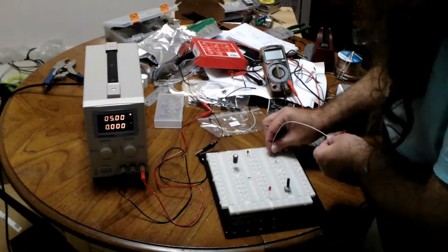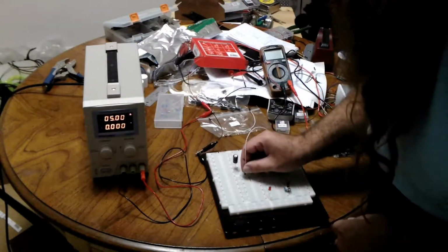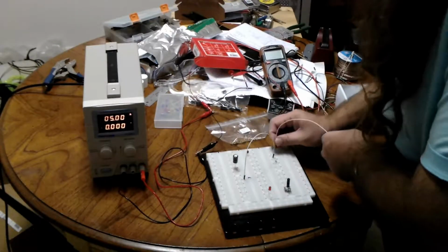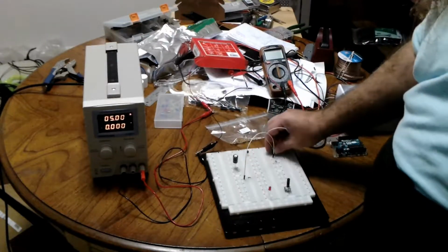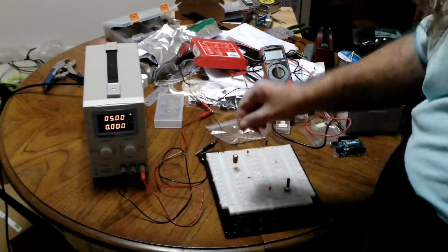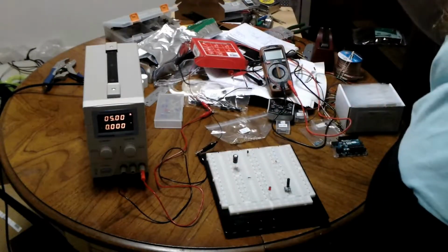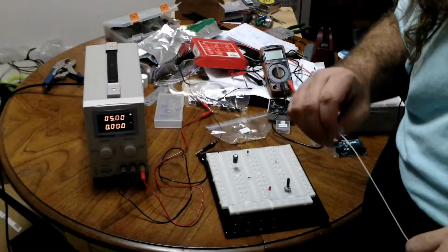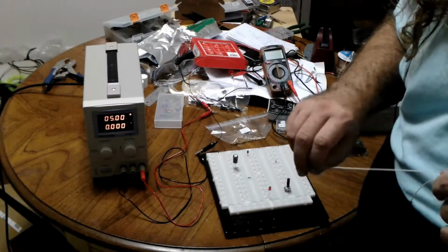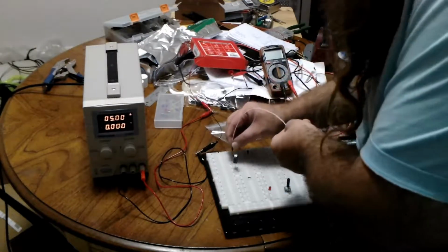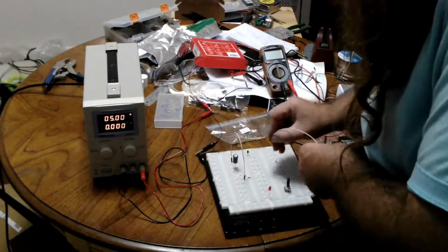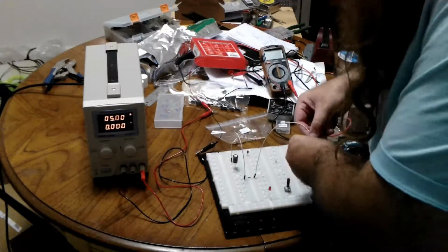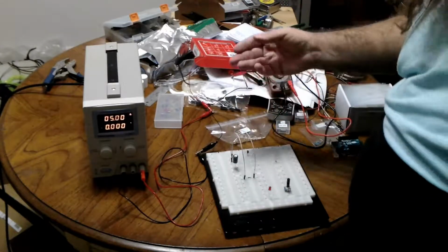So one end of this other capacitor, the smaller one, to one end of the resistor, and then the other end of the capacitor to the other end of the resistor, and now it's just discharging. Because the resistor does resist the flow, but it scales, basically, by Ohm's law. It doesn't really taper off anywhere near as much as the LED, because the LED has its voltage drop and so forth. So we'll connect this, and now we're discharging the capacitor through a resistor. The resistor is nonpolar, so it doesn't matter which way we do it. So do that, wait a couple seconds, and you're good.